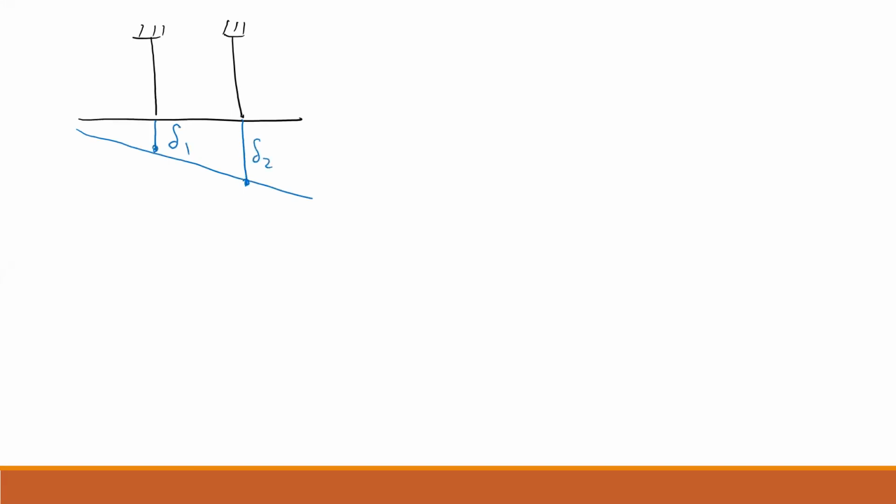But we can go ahead and look at our kinematics. If this is our initial setup, we're going to have some deflection, and it's going to be more so towards where the individual is standing. So this is highly exaggerated, but this would be our del 1, del 2, and then del 3 is where the individual was standing. And the way that we're going to relate these is through similar triangles.